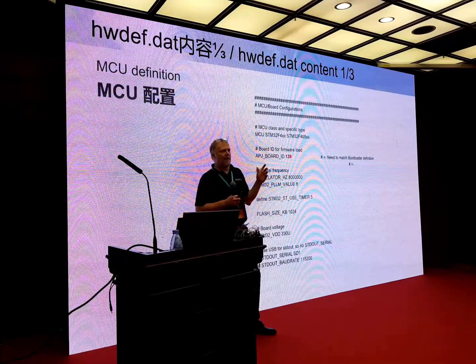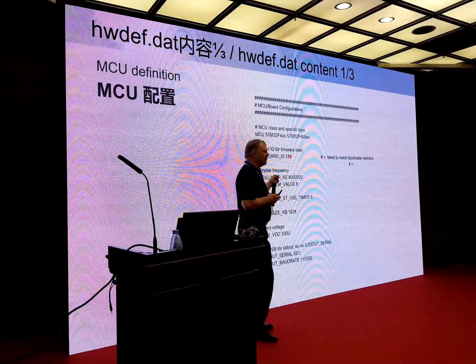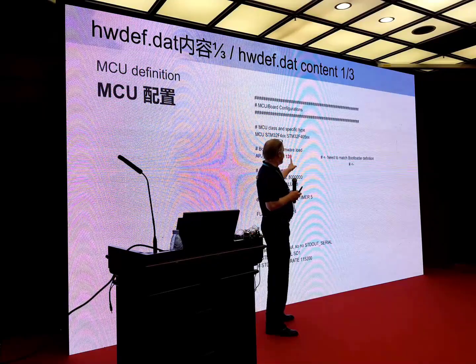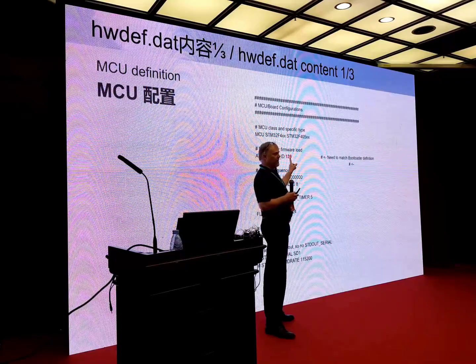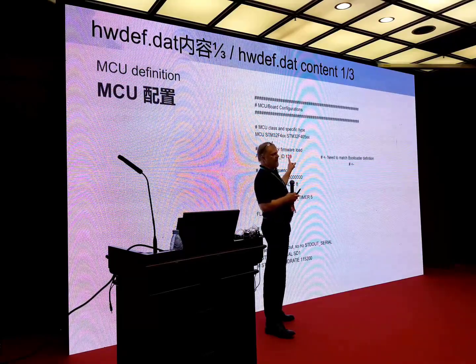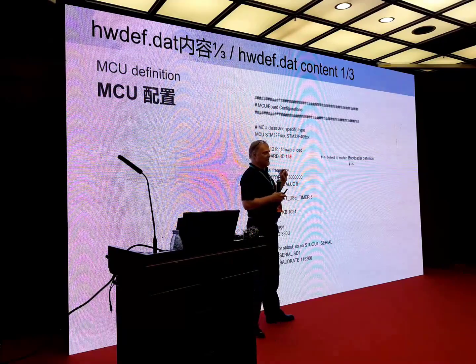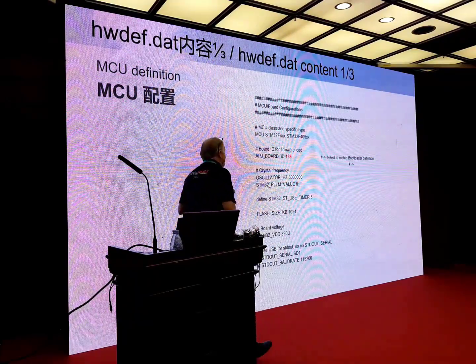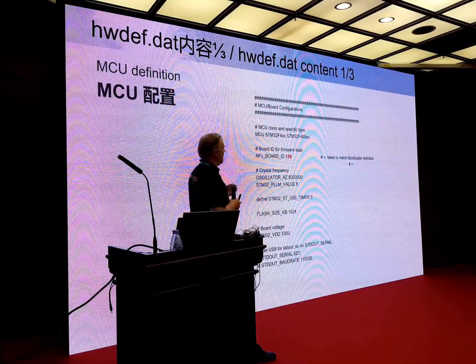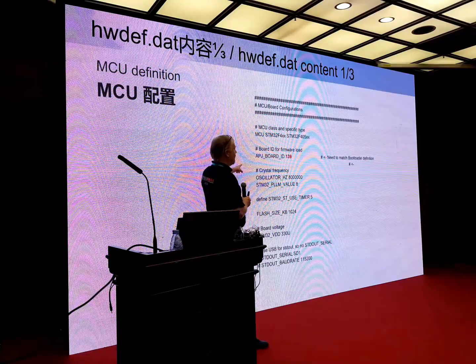Earlier I was talking about that bootloader and the board type. So this is the number that has to match the board type file in the bootloader folder. If you have a mismatch in here, your system won't work. And basically, all different hardware should have its own board ID.